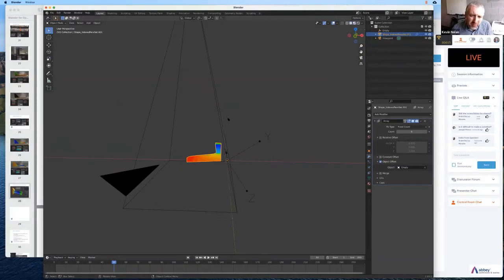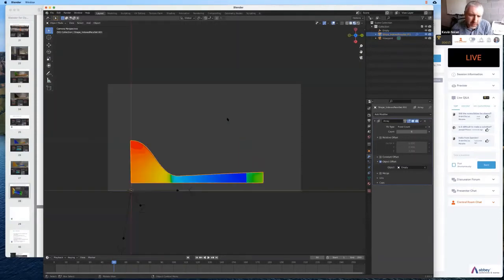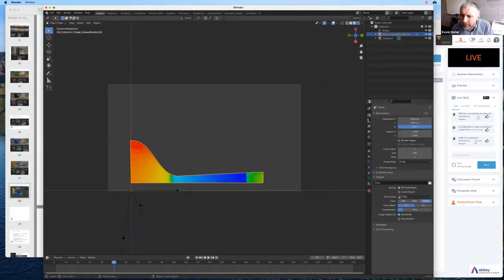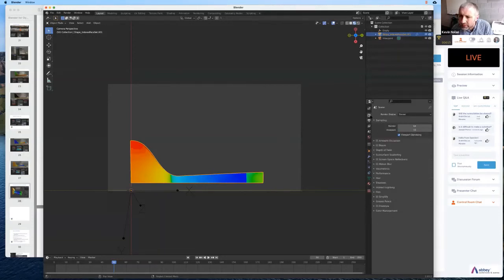And then what I want to do is I want to export that out. So I can just go to my viewport here. I can go to my output, my printer icon here. I can specify a resolution here, so this is 1080p. A folder where I want to put things. By default, it's your temp folder, and it outputs PNG files by default. And then under my render settings, I can specify which engine I want to use, EEVEE or Cycles.